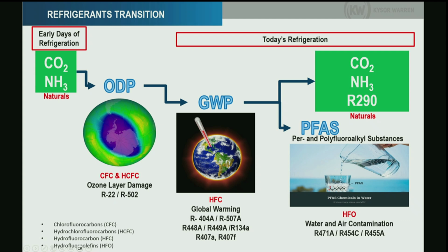CO2 as a refrigerant is good as well. The problem with CO2 in the early days is that it's a high-pressure refrigerant. When I say high-pressure, it's about more than 10 times what you will see with HFC systems. So that was the downside at that point.